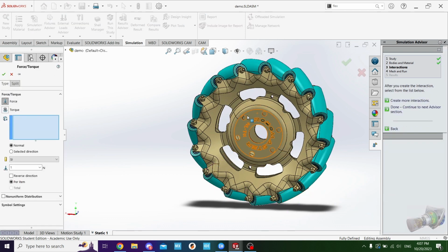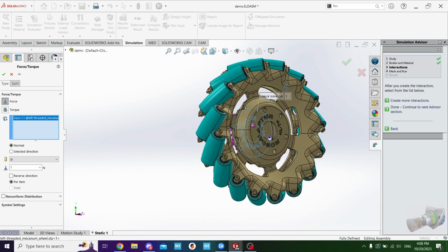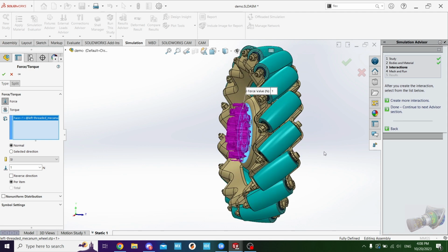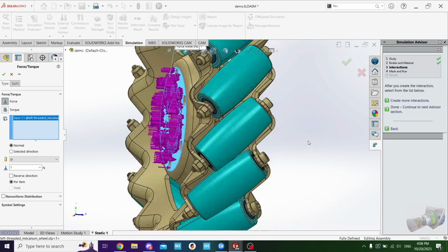So you see, there's a force and then there's torque, right? Let's select this surface right here, and just hover, click it, and get your mouse out of the way. Now rotate the view. So now you can see how all the arrows are pointing this way. It tells you the direction in which the force is applied. So you have the force, the surface you're applying the force on, and the direction, which can be normal to the surface you're selecting, or some other direction at a fancy angle. Force, do 100.